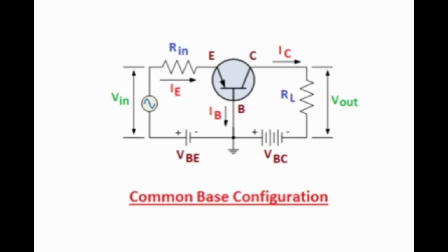Current at the emitter side is quite large, where electrons are diffused into the base terminal. These electrons pair with some holes present in the base, while most of them leave the base and are collected by the collector. This type of transistor comes with remarkably high voltage characteristics, which don't make it an ideal choice for many applications. In this configuration, the output and input voltage are in line with each other. The input characteristics of this transistor are quite identical to a forward bias diode, while output characteristics are similar to a regular diode and come with a high output to input resistance ratio.